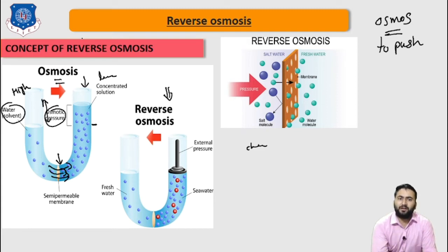To desalinate water, it is required to create flow through a membrane, causing the water to leave the salt side of the membrane and pass into the unsalted side. To achieve this, pressure must be applied to the water column on the salt side of the membrane: first, to overcome the natural osmotic pressure, and secondly, to create extra pressure on the water column in order to push the water through the membrane.